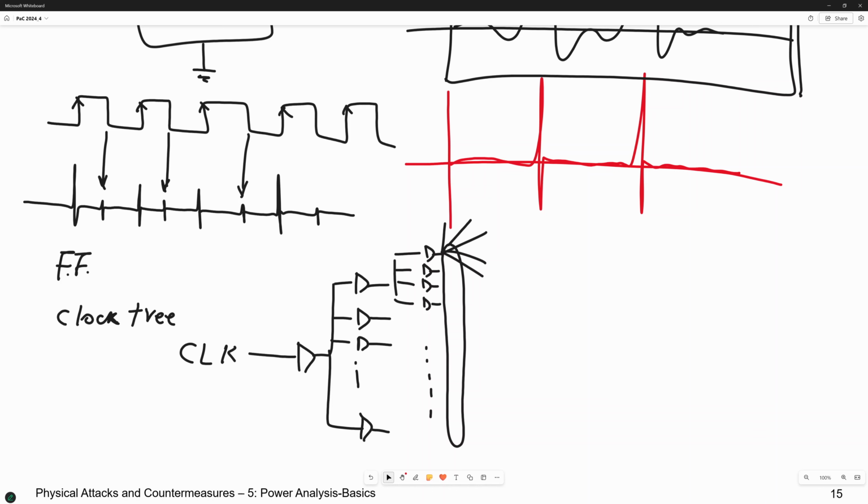And then you have to get the output from this tree at the same level. All of the registers should be supplied from the same level or depth of the clock tree. Otherwise, there will be a race, meaning that some flip-flops get triggered earlier than the other flip-flops, and the circuit does not necessarily work correctly. Yeah? This is called a race issue, race problem.